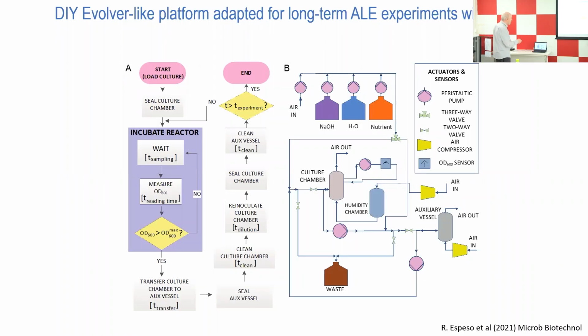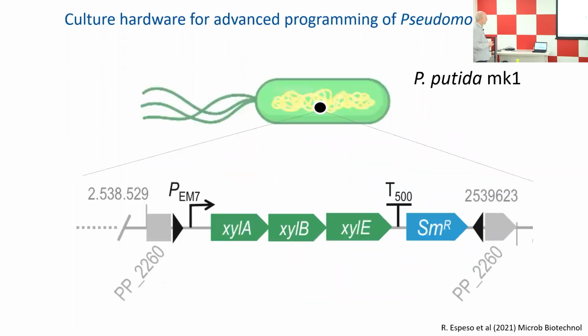So in this case, for instance, David developed a concept, which is to have the reactors flushed every 24 hours with sodium hydroxide, and by doing that we ensure that any remaining cell stuck to the surface of the reactor will be eliminated. Obviously, this was again washed and everything, and then you can maintain this operation for months and months and months, and still maintain a degree of sterility and avoid the formation of biofilms. Okay, so there's a kind of branch of synthetic biology that has to do with the development of good reactor setups for this type of evolutionary experiments. That is quite interesting.